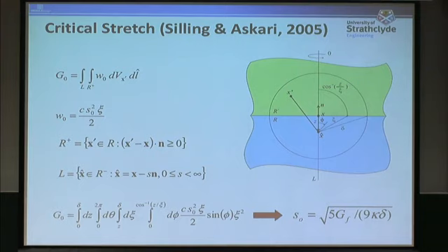So again, you are trying to represent the definition of critical energy release rate, nothing else. I was a little disappointed that we saw a qualitative comparison. Suppose you took Broberg's problem, 1960, dynamic expansion of a crack from a point. Not quite the first dynamic solution, but you could have compared your solution with that, because that's an elastic solution. If you made a comparison, would you get the same solution? Because it's not enough to show qualitative comparisons like that.